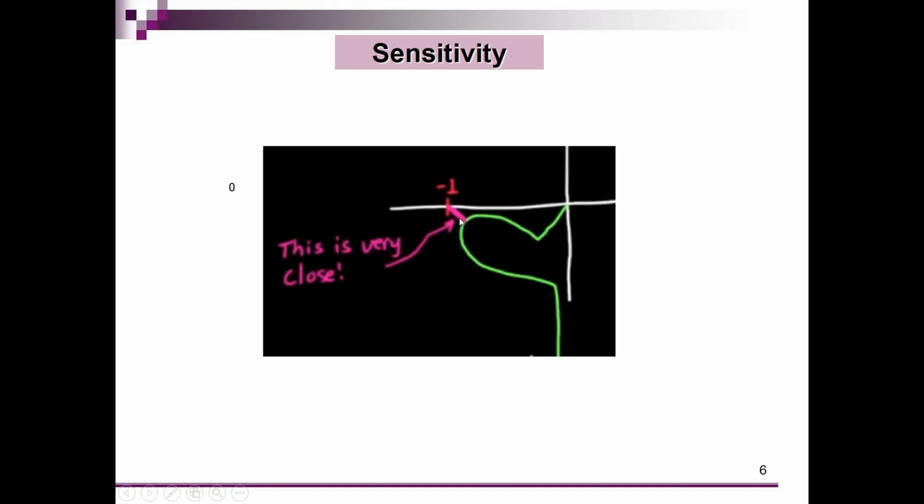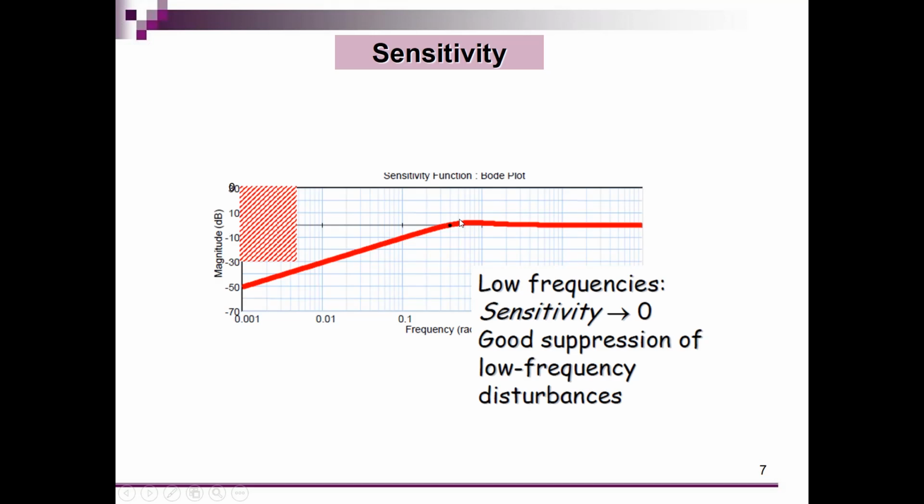That means that when you look at the Bode plot of the sensitivity curve, we have a requirement on the maximum value of that sensitivity plot, which is often a factor of 2, which in dBs is 20 times the log of 2, which is 6 dB. So we always have to be sure that this amplification over here isn't too high.